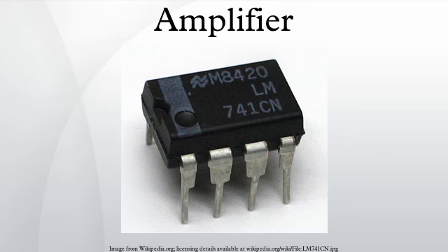All amplifiers are bilateral to some degree. However, they may often be modeled as unilateral under operating conditions where feedback is small enough to neglect for most purposes, simplifying analysis. Negative feedback is often applied deliberately to tailor amplifier behavior.